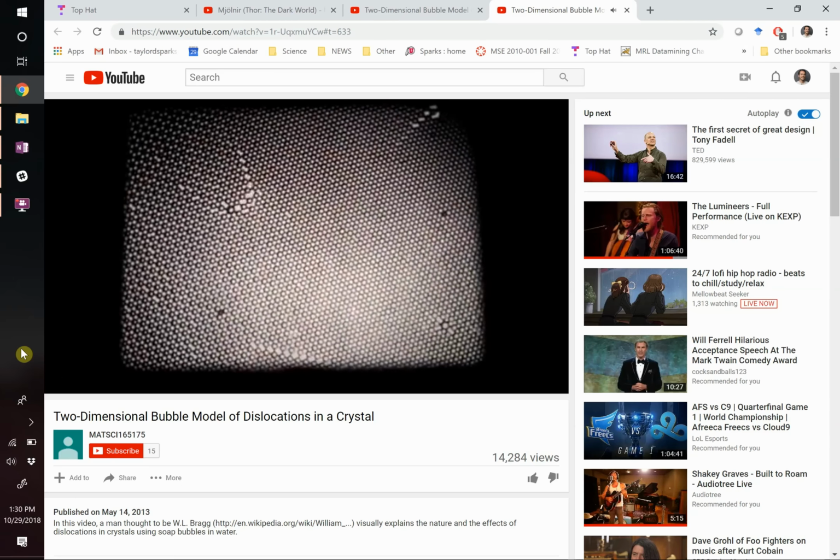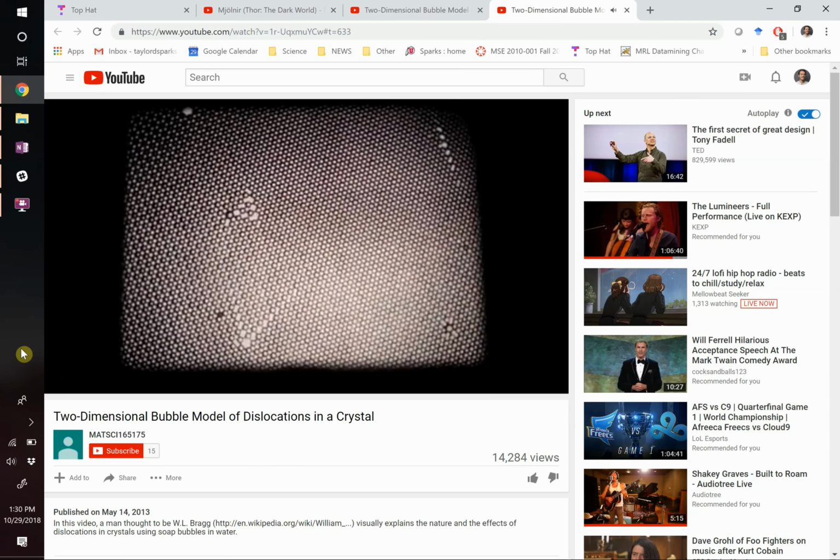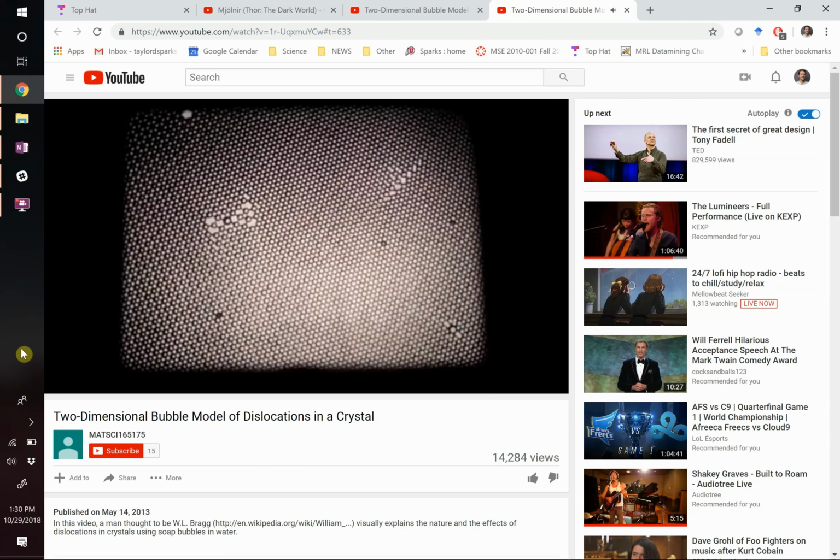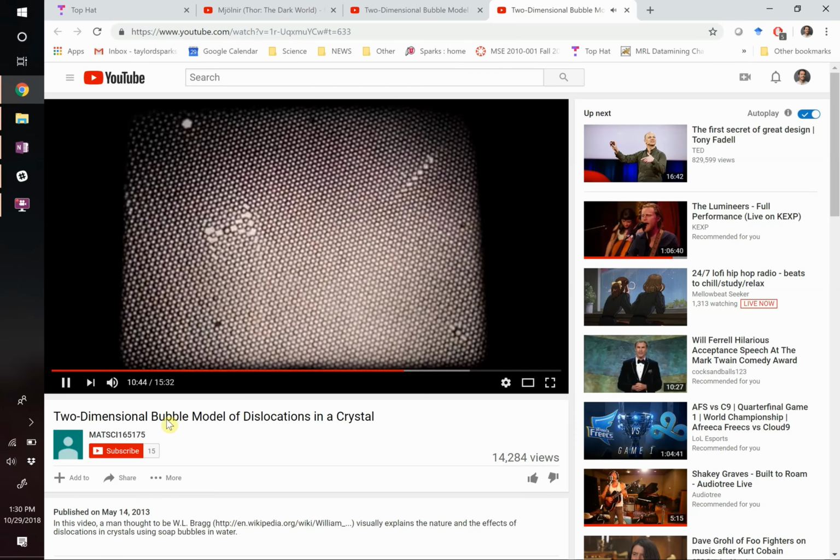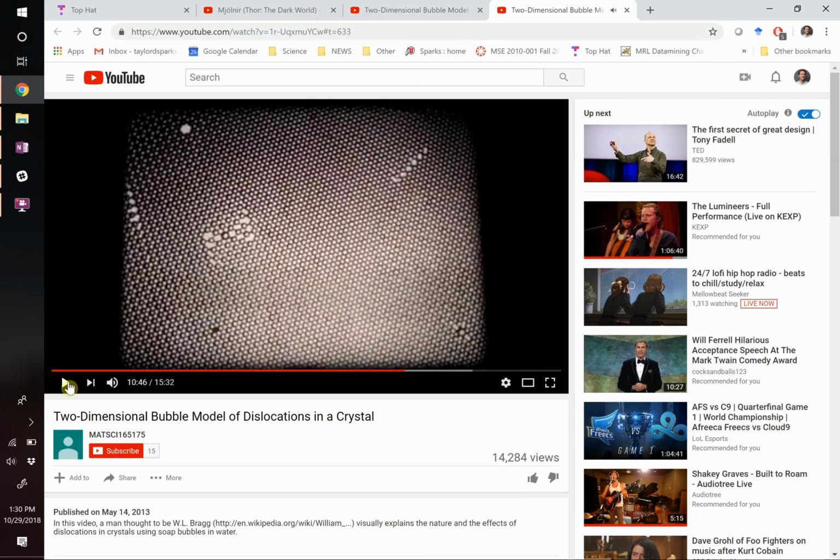Okay, so the dislocation comes by. It's going to come by again, and it's stuck. Now it's stuck on the other side, but of the opposite sign. Do you see that? You've got two dislocations of opposite sign coordinating that defect. So you've got the two tensile regions of two dislocations clumping up near that compressed region because overall it reduces that strain.